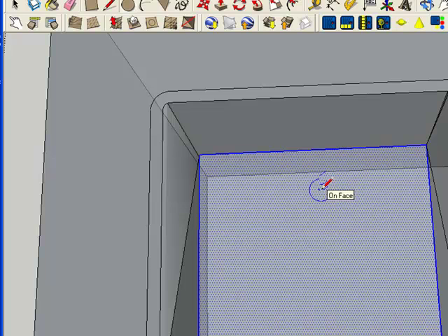I don't want it to tip, so I'm going to hold Shift, find the center place, let it sit there for a second or two, come down to the other line, find the center, and let it sit there for a second or two. And then usually when you come back here, there you go. You can see where the two cross, and you're actually exactly in the center of that space. So I can let go of the Shift key, click, and draw the circle.